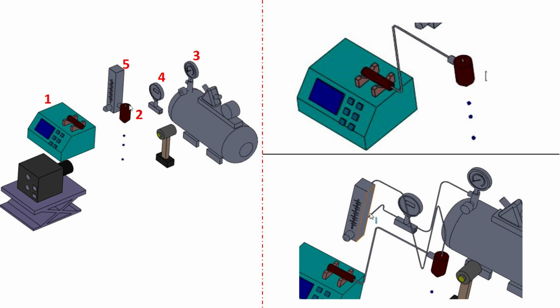Suppose I will connect part 1 and part 2 as shown in the top right side of this slide, and also I will connect 3, 4, 5 and 2 as shown in the bottom right part of this screen. I will use both the 3D sketch and the swept boss base feature of SolidWorks. I will explain every step and the step by step procedure of how to do it.